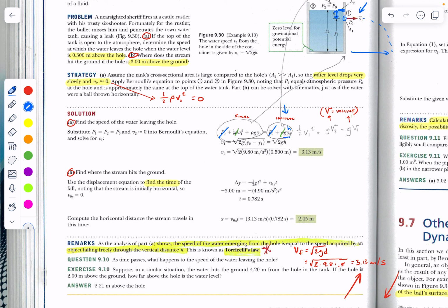And then where does that energy go? Well, all of that energy goes, if we have an ideal fluid for the most part, towards having less potential energy because you're farther down the tank, and you're going to also have a kinetic energy per volume. And so when we cancel out the density of our water, we get this equation right here.